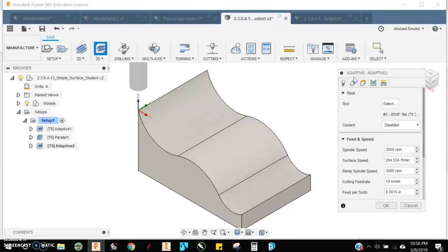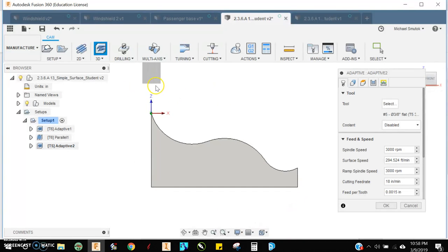With a 2D toolpath, the tool goes down in the Z and then it does all its X and Y moves, and then it goes down in the Z and does all its X and Y moves. Well, the way this is going to operate is it's going to do X, Y, and Z at the same time, sort of. As a result, it will calculate that this tool, if I look at it from the side here, will figure that this corner isn't going to touch anything that you want to be finish machined. So you're going to end up leaving a lot of extra material, and I'll show you what that looks like.